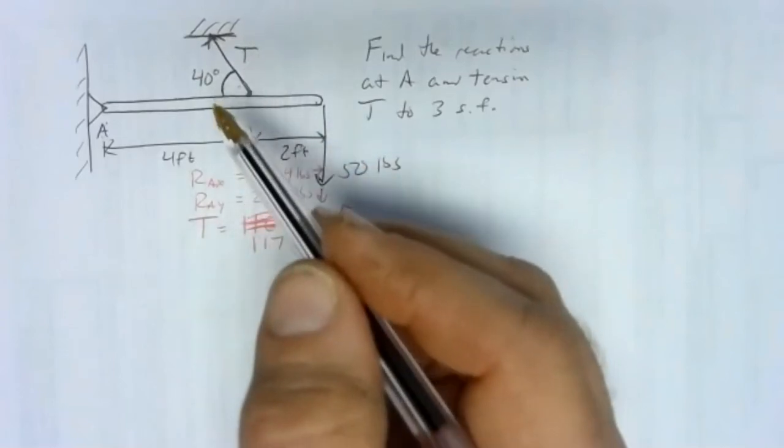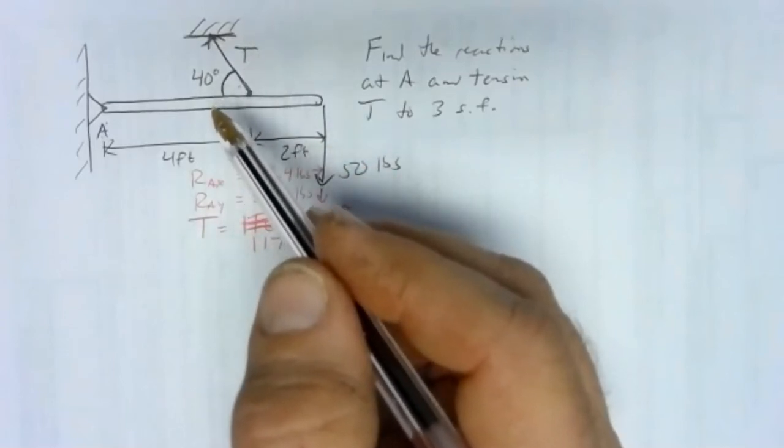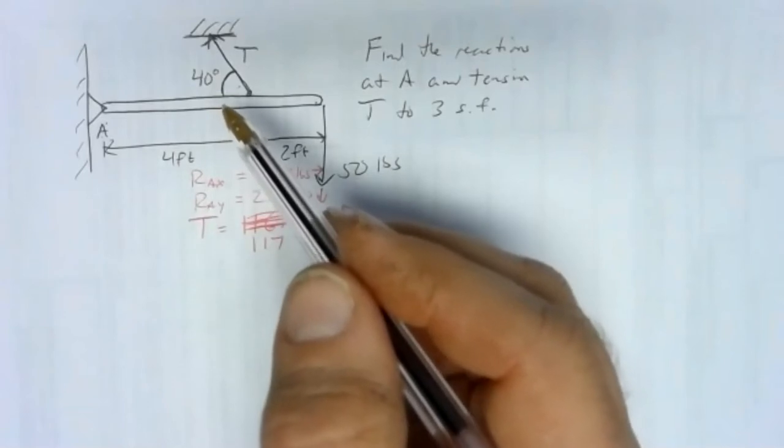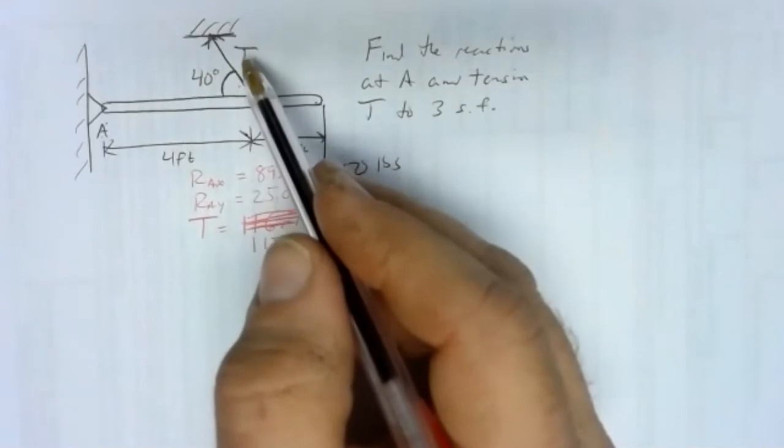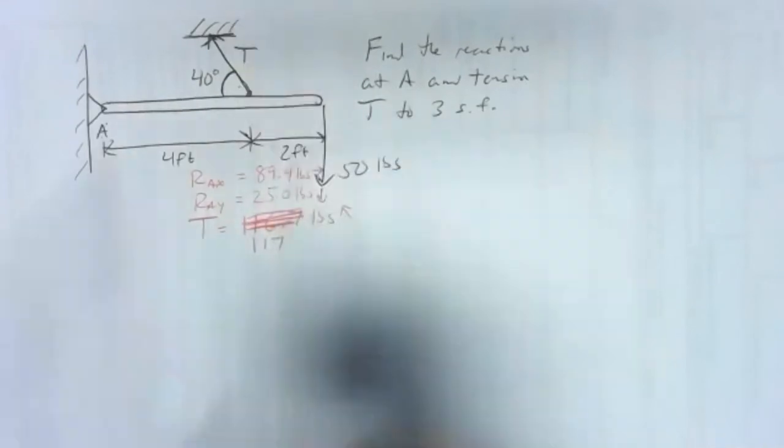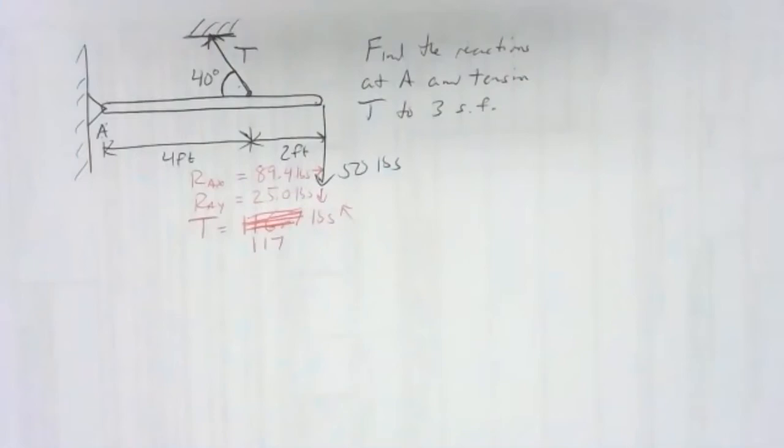It's kind of like on an airplane when we go into a bank, and the lift is now tilted off at an angle. That same lift doesn't support the airplane anymore. We have to increase the lift to stay at a level attitude or level altitude.